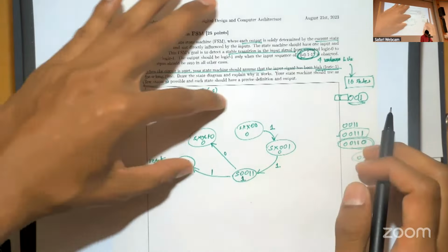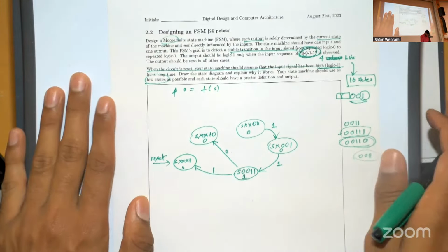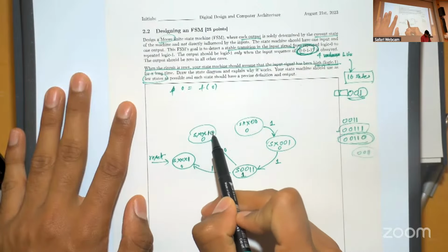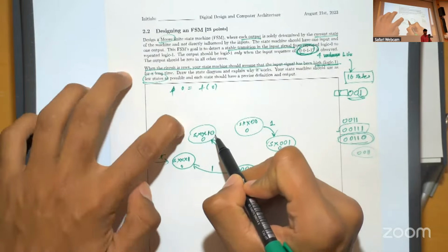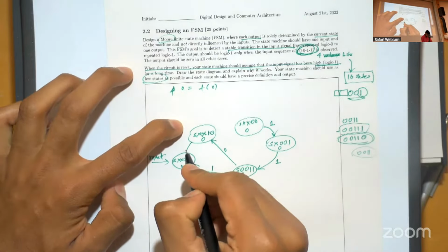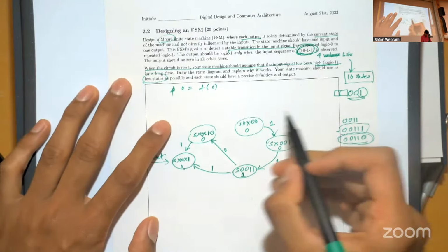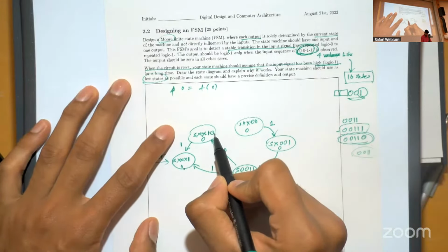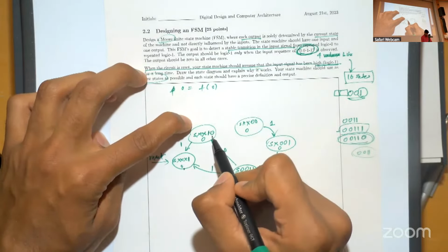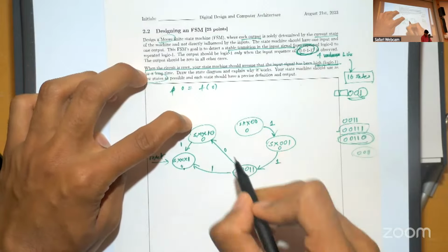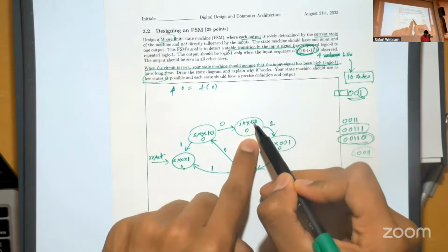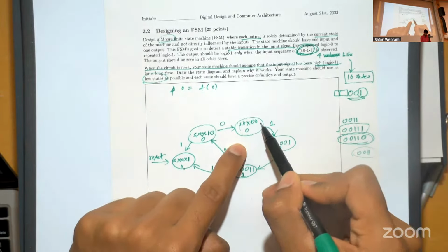All right, so we have these states. And now our job is to complete the diagram. At this point, when you see 1, 0, if you see a 1, you go back to this state because this is the last one, right? So this is where it goes when you have a 1. If I were to see a 0, then this sequence now becomes very interesting to me because you'll have a 0 and a 0 following it. So it goes to this state on a 0. We haven't handled what happens when you see a 0 here. What happens when you see a 0 here?